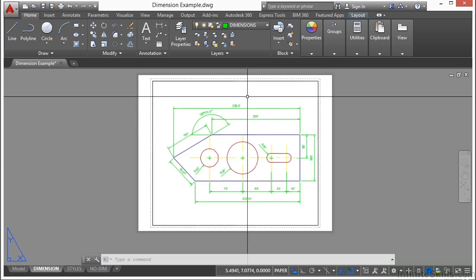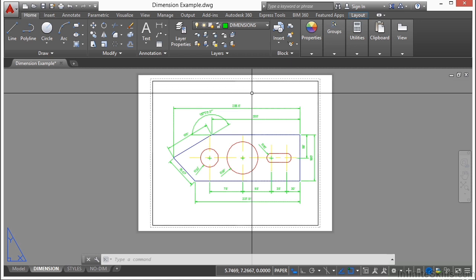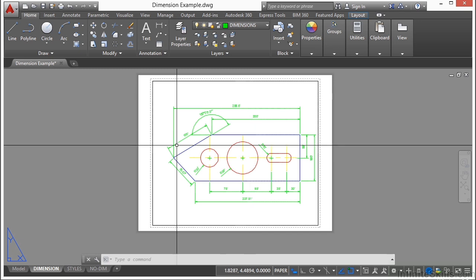We have no line work. We just have the dimensions and the viewport that visually displays the model for us in Paper Space. This is a very simple example, but very clear as to what's going on, because sometimes the lines between model and paper space can be blurred. Let's make a new layout tab.